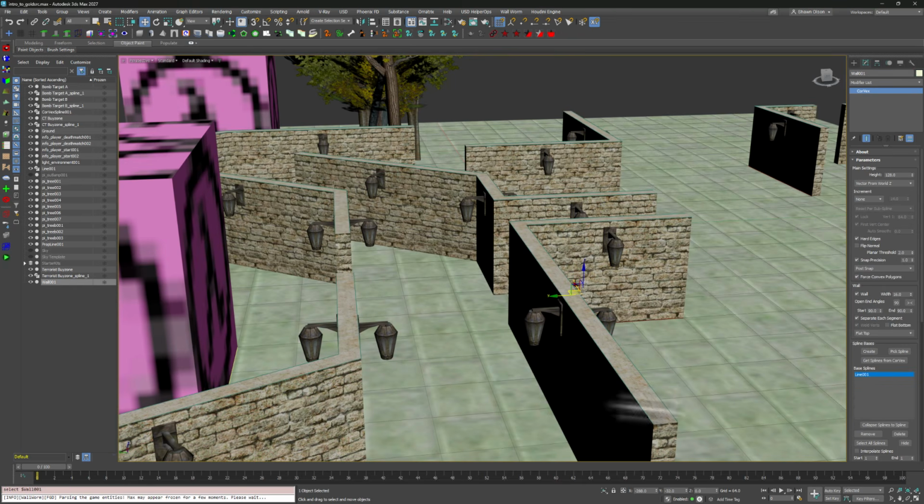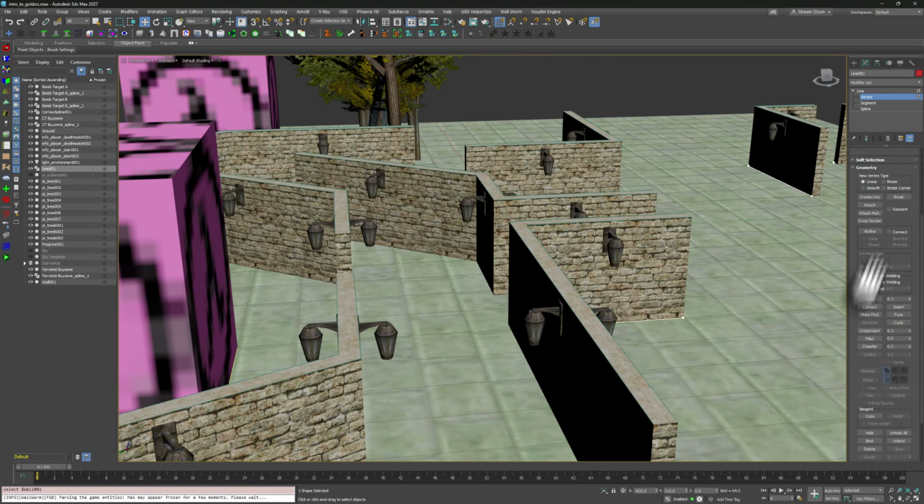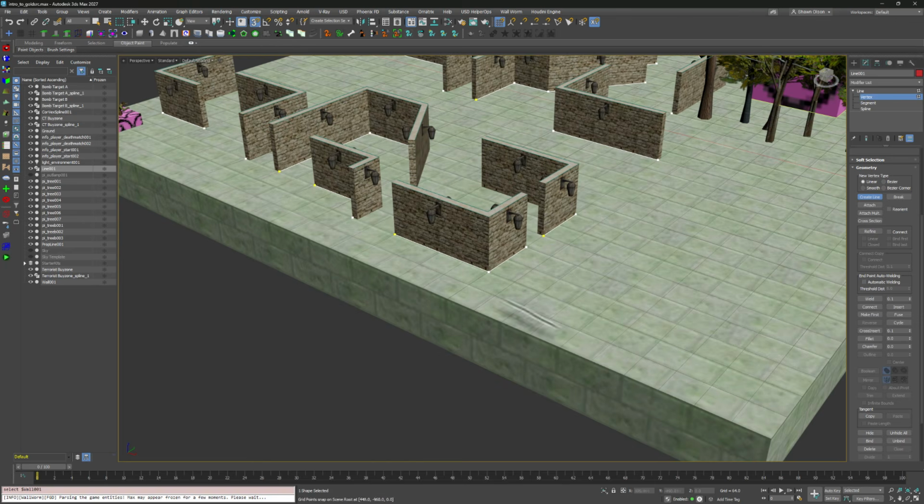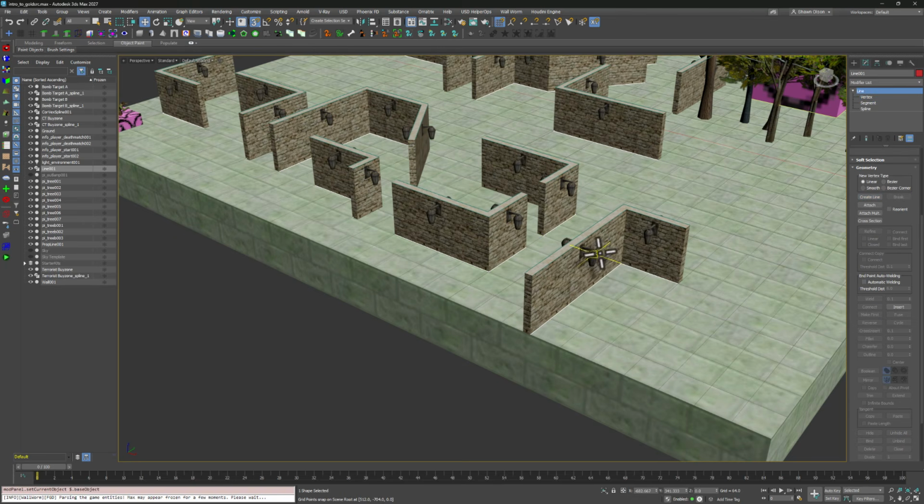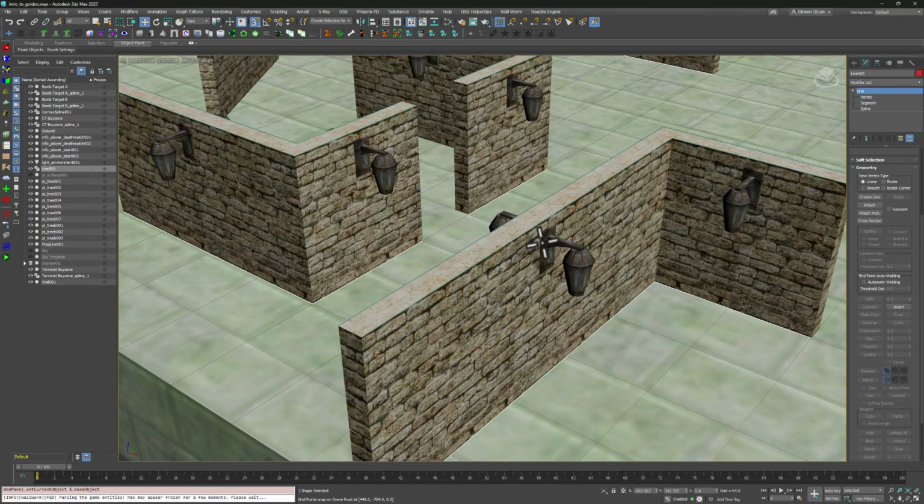Once the alignment is correct, let's go back to the spline controlling the CurveX and add more walls. The prop line will not auto-update while editing that spline, but as soon as you exit subobject mode, the props will scatter on your new wall, as you see here.